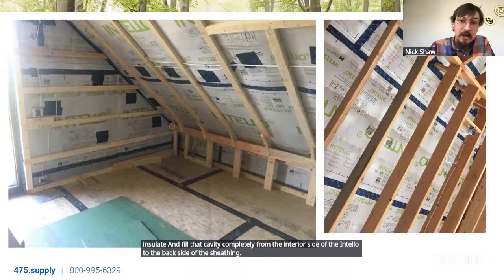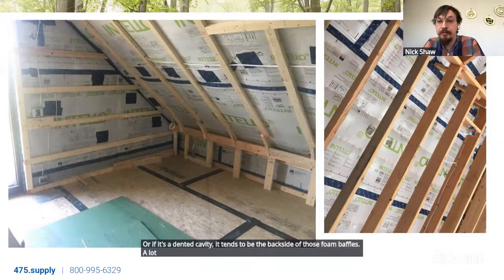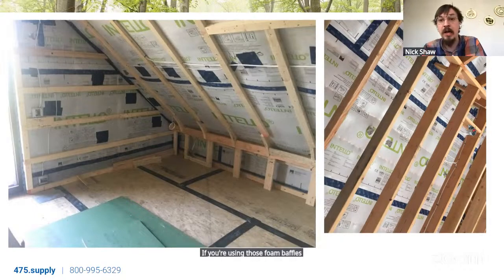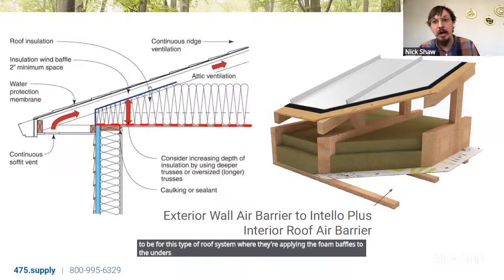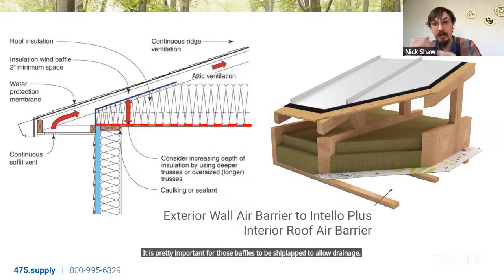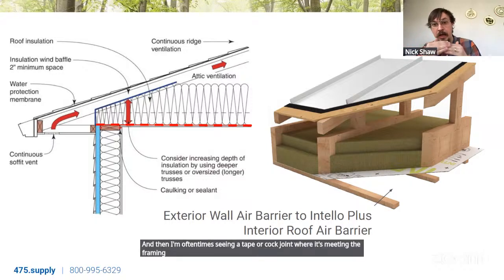Or if it's a vented cavity, it tends to be the backside of those foam baffles that a lot of folks are using. If you're using those foam baffles on the underside of that sheathing, it tends to be for this type of roof system where they're applying the foam baffles to the underside of the sheathing. It is pretty important for those baffles to be shiplapped to allow drainage. And then I'm oftentimes seeing a tape or caulk joint where it's meeting the framing and at the connection points.